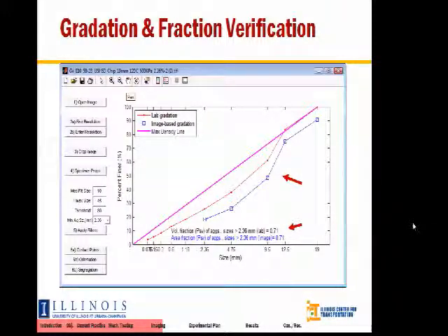So after the processing phase, what are we seeing for those individually numbered regions? Okay? What is the total area of those? What is the equivalent diameter of each of those identified regions? So we end up with an image-based gradation. If they don't agree, whether the gradation or the volume fraction versus area fraction do not agree at this stage, you need to adjust your filters that were used during the processing phase. Okay? So this is to allow people of multiple experience levels in imaging to actually process the image and come away with a little greater confidence that they have processed it appropriately before analyzing an image and wasting time on something that was not properly processed.